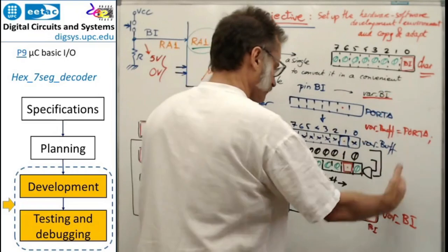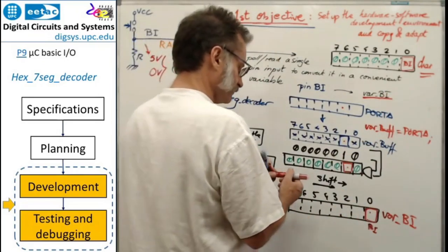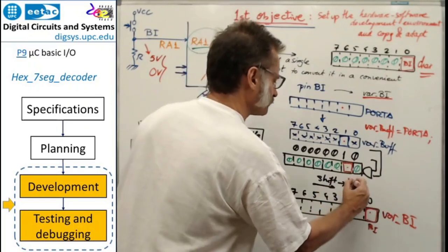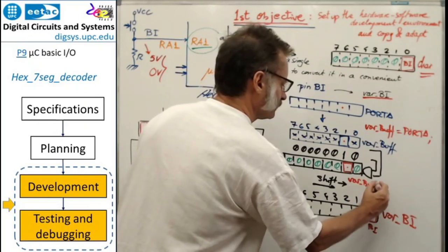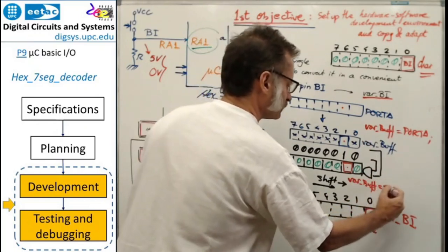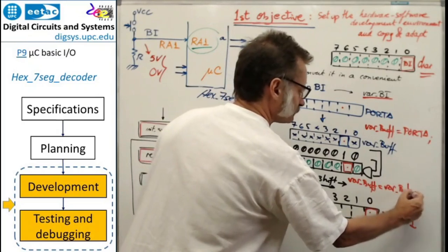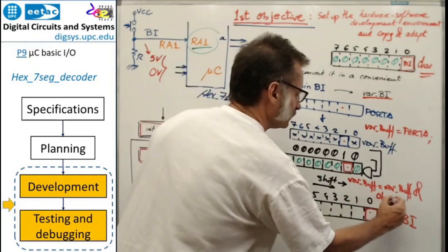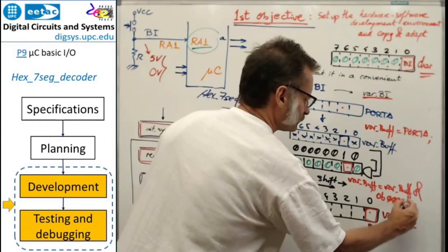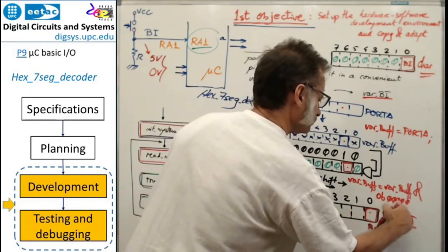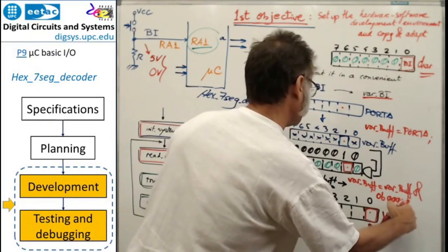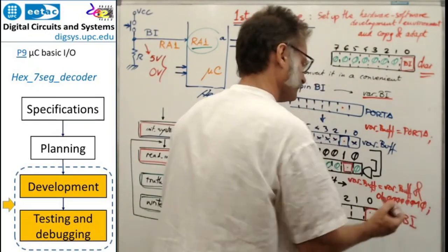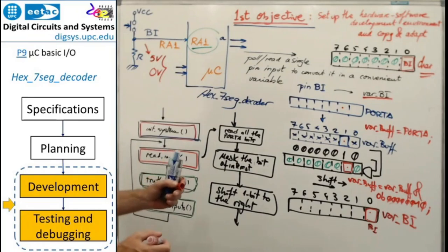So if you've got all these pictures now on your paper, it is easy for you to write, for example, another instruction in C, the one belonging to the masking, which is something like bar buffer is the previous value that was bar buffer, and you see that is the ampersand, and then 0b 0 0 0 0 0 0 1 0, that's the mask, and semicolon. This is the text that you have to type in the C source file.